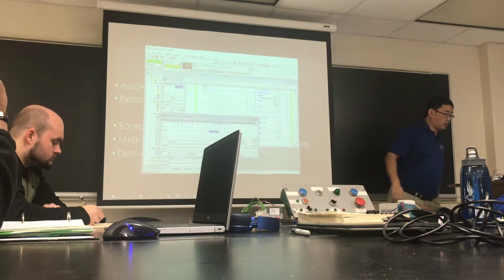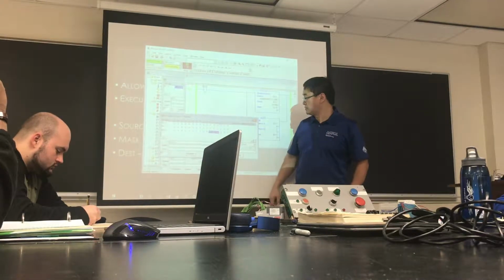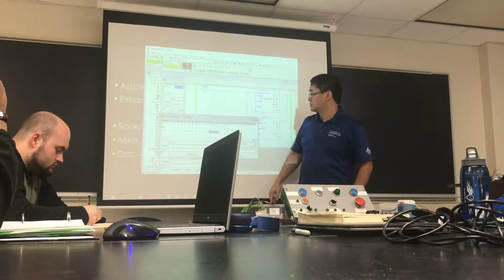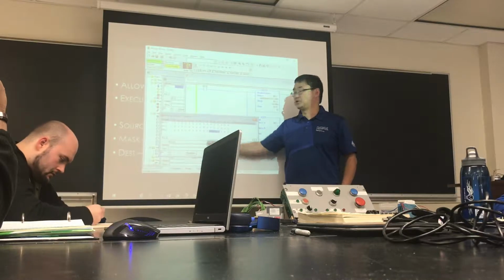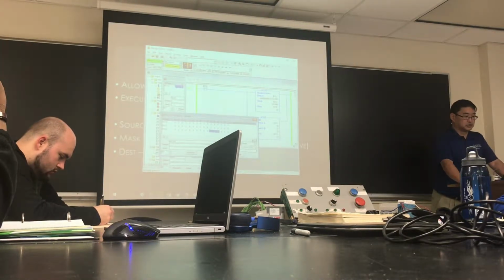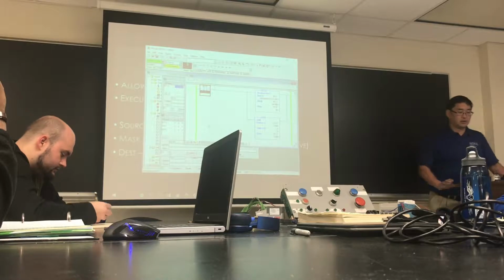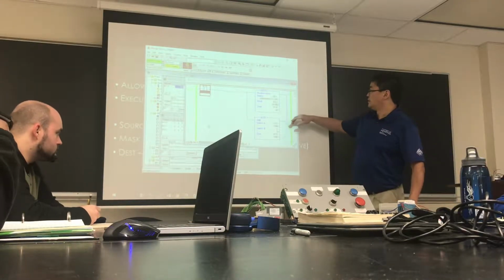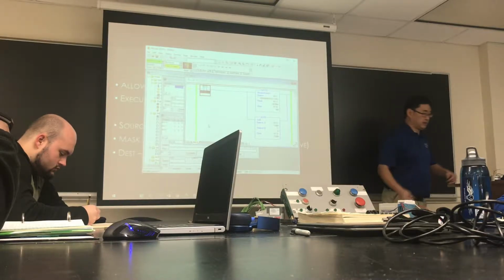And so when I enable this, it's going to put 124, apparently, into N7. And it's going to ignore that bit right there. Actually, it's not going to put 124 in. It's going to put only those 3 bits, which is less than 124. And so let's just do it. And so it moved, instead of 124, it moved number 56 in.